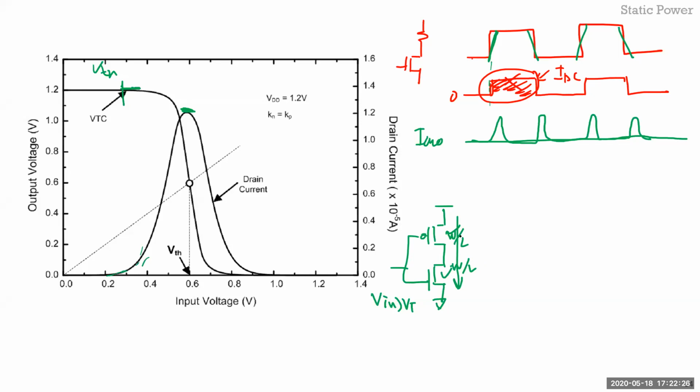Here, it will be whatever your saturation currents are. The same with the resistive loaded RL2, except that the RL is just a linear resistor. And then as you transit slowly to 0 volt input high, it obviously starts going down. So that's your static power consumption over here.